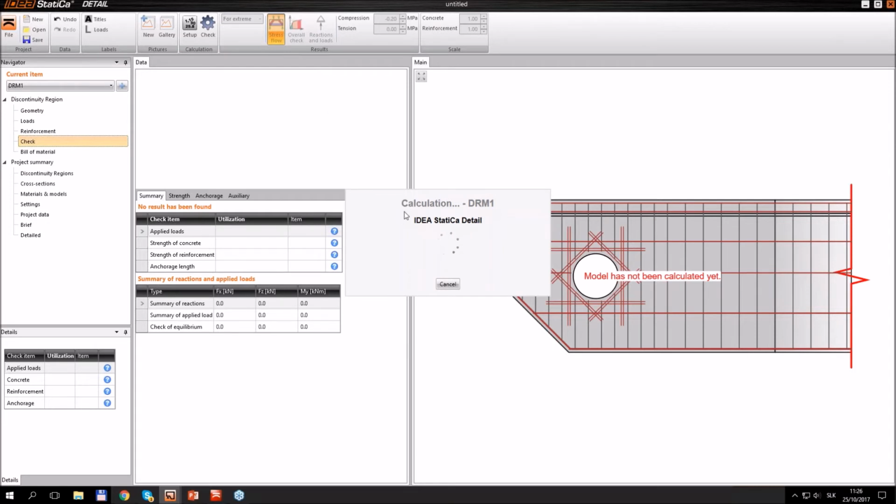At first we will load the model with the permanent load case, calculate the stress level, and then apply the increments of the variable load, right? And this is how the calculation is done. After a few iterations, we will get the results in a very nice way, which we will explain. It plastifies a little bit now, but in a few seconds we will get the results.